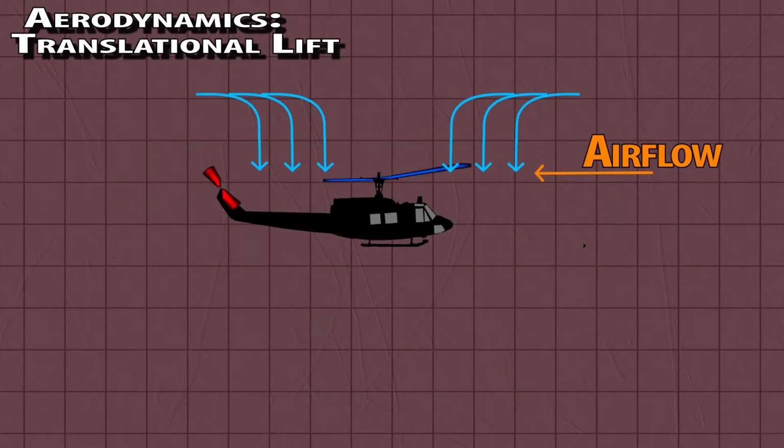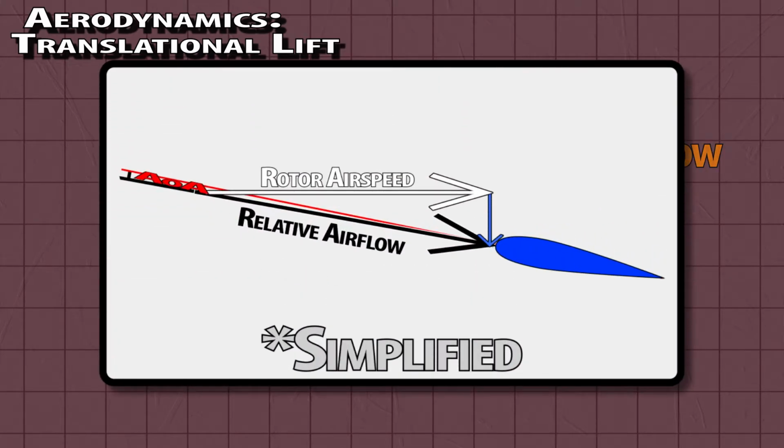Air coming in from the front, either from a headwind or forward motion, will blow across the vertically induced column of air and change it before it reaches the disc. We still have a downward component, still have the induced flow, but less so than before. So we know air moving in horizontally with the rotor disc reduces induced flow.